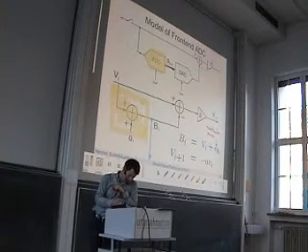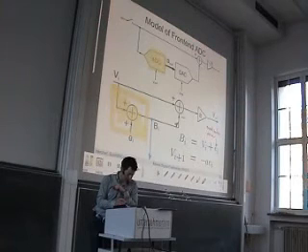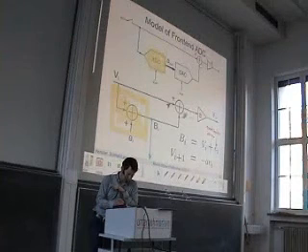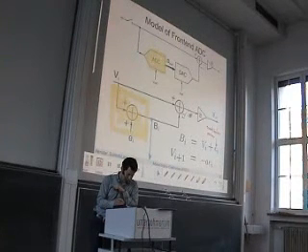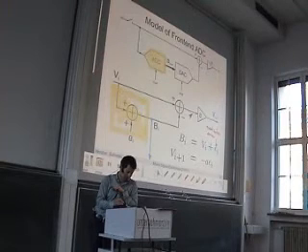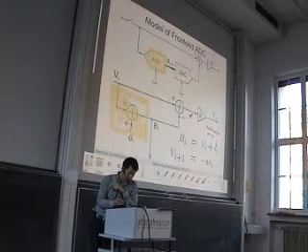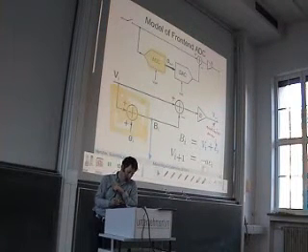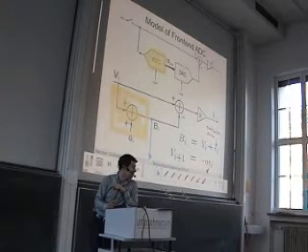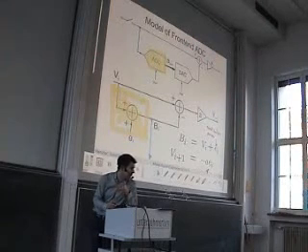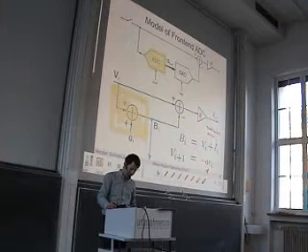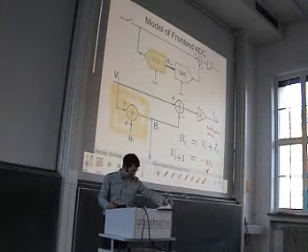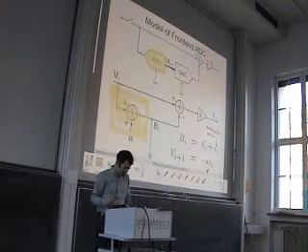Okay. If we assume that we have here V plus E, and we subtracted this from V, then we get here the quantization error, or minus the quantization error, and this one is scaled by this factor of A. So at the output we have minus A times E. Minus A times the quantization error. And this is very useful to understand how we convert this back.